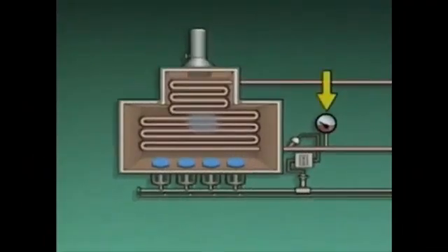If the outlet temperature goes down, the outlet temperature controller will trigger an increase in fuel flow to the burners. But this only aggravates the problem. If this extra fuel doesn't get burned, the outlet temperature is going to keep dropping. Besides the drop in outlet temperature, the insufficient airflow can lead to another problem.